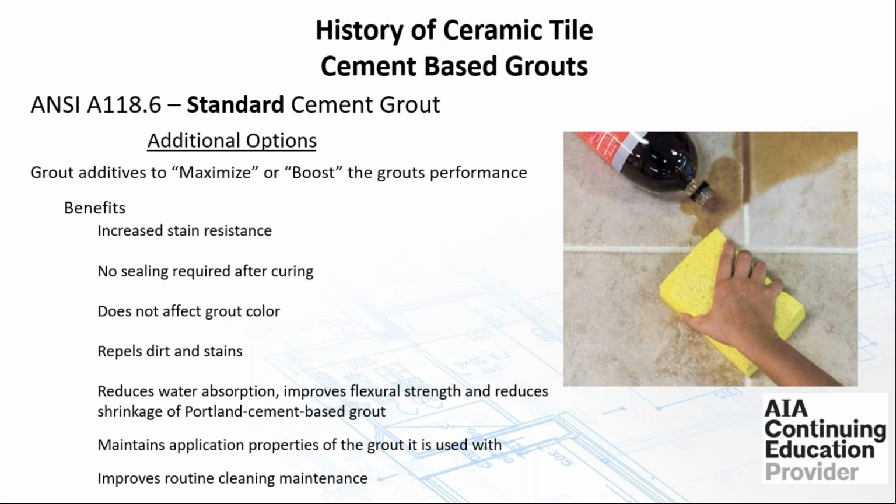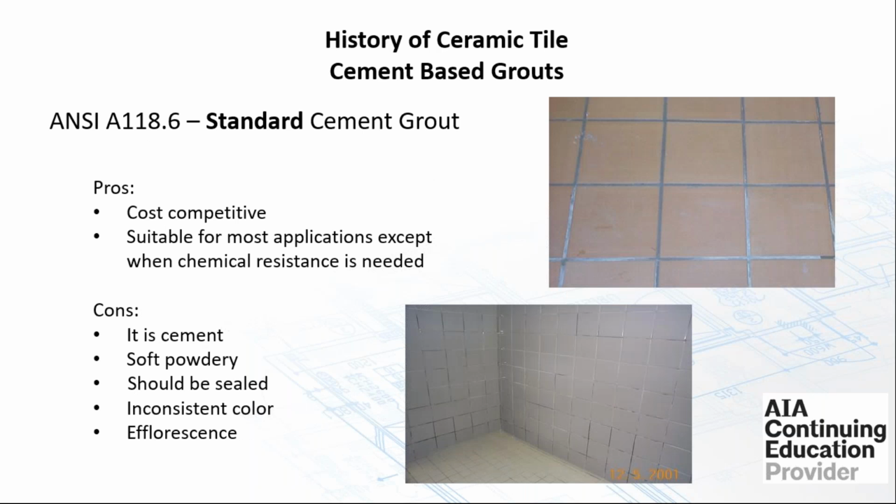It does also help with improved cleaning and regular maintenance of your Portland cement by adding these boosts or these additives into the Portland cement grouts. The pros of using a Portland cement grout, or grouts that comply with ANSI 118.6, they are cost competitive. They're suitable for most applications except when chemical resistance is needed.